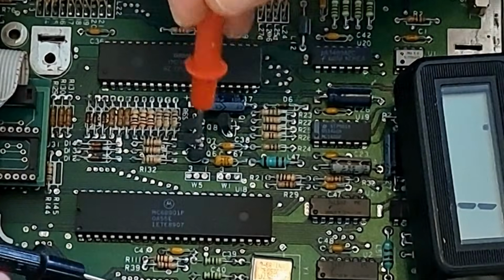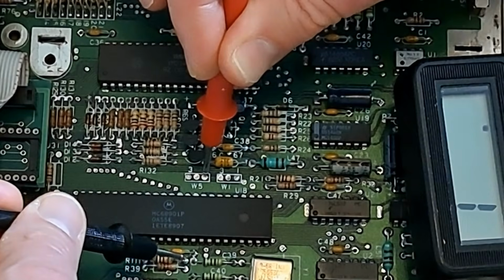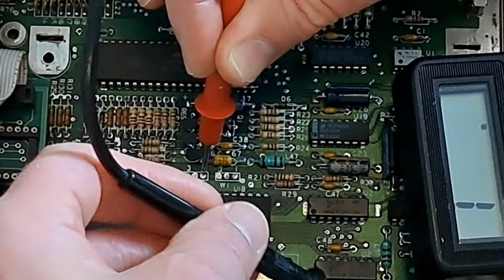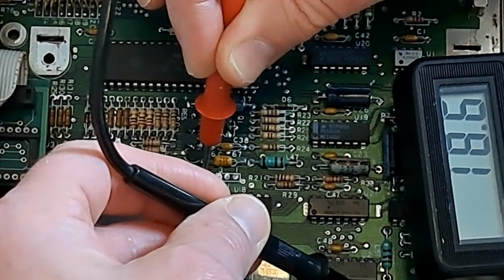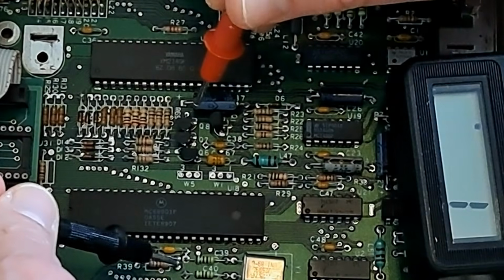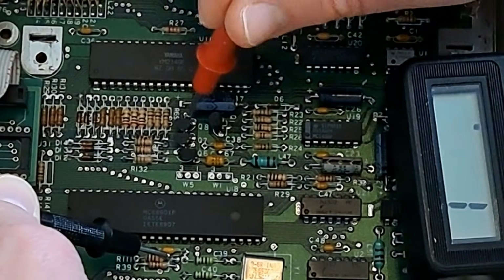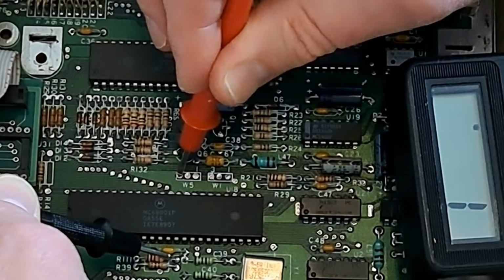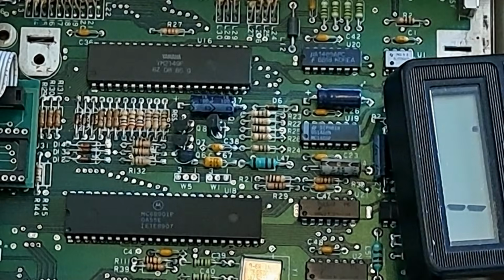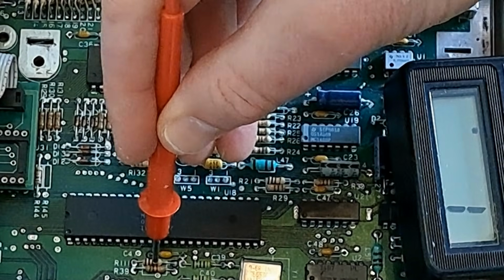Okay, here we go again. I'll take pin 1 of W5 now, that's connected to pin 3 of W1. And here is U79. And indeed, there's a connection to pin 3. And here is R111, which is connected to the plus 5 volts. That should be connected to the other side of the jumper. And that's correct. So the drive select of the second external drive is connected to the positive 5 volts here.